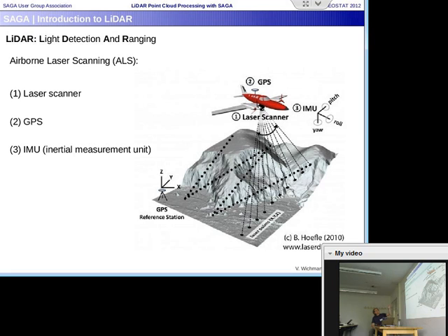You see that all these measurements must have a very high precision, and that's actually still the problem, which is limiting the actual precision of the coordinates. Because once you have a bad GPS signal, you will not have very accurate plane positions, and then you get errors of the point locations. So with evolving technology, it's getting better and better, but this is the limiting factor. And actually we have precisions of about a few centimeters, horizontal and vertical.